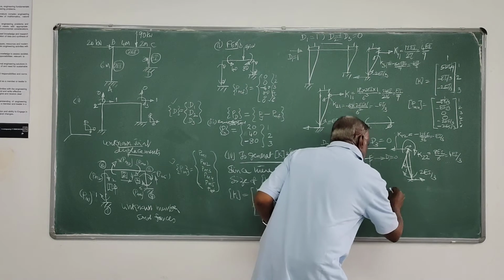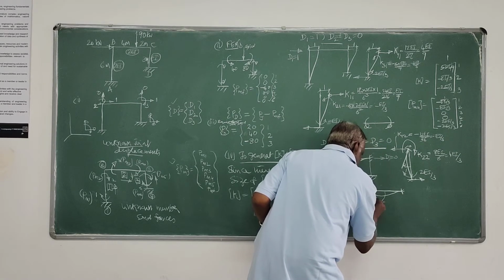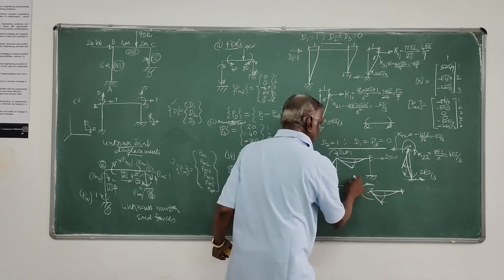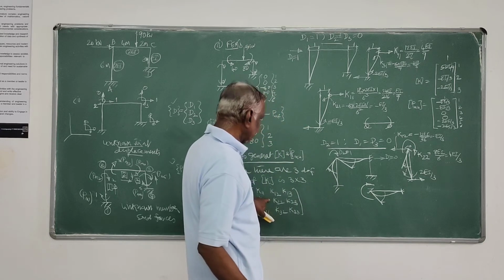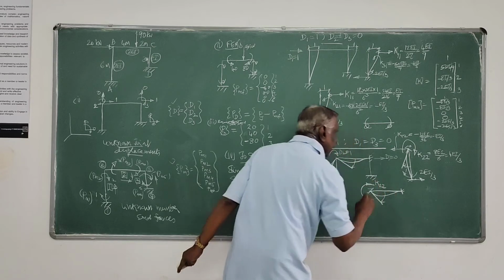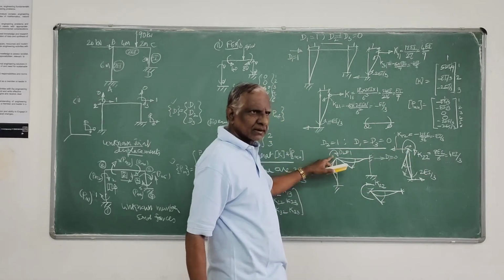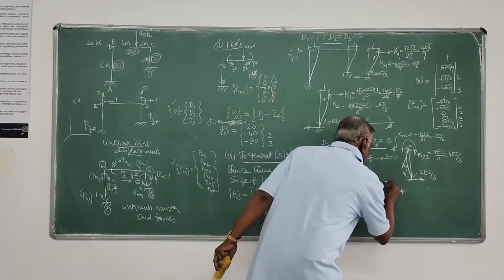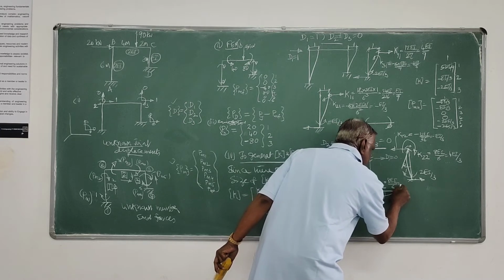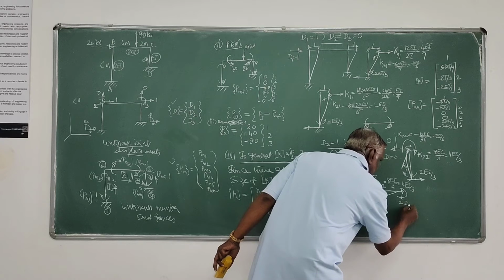Same thing, this member that is also getting affected, so that it moves in this fashion. So here, same formula, that is 4EI by L. It is the moment generated. So this particular matrix coefficient, that is stiffness coefficient, corresponds to 2. This corresponds to 2 when unit displacement is given at 2. This also K22, because both are same joint B. So that is rotation corresponds to same 2. So this is 4 into 2EI, 8EI divided by L is 6. So this is also 4EI by 3. And at this joint it will be half this value, that is 2EI by 3.